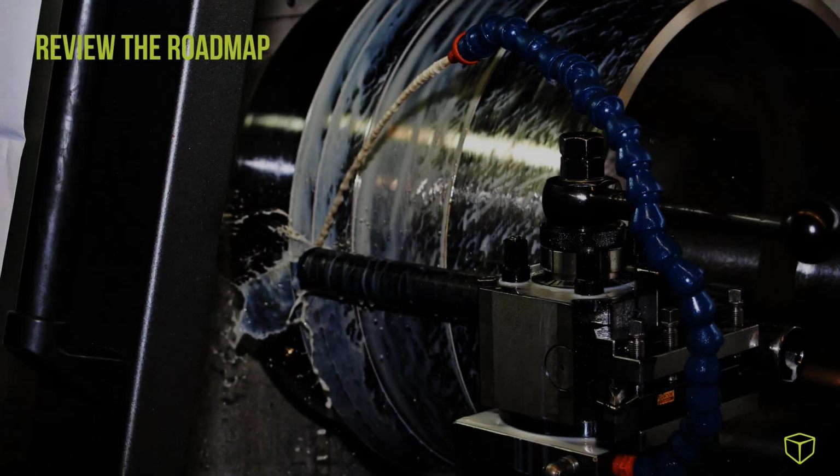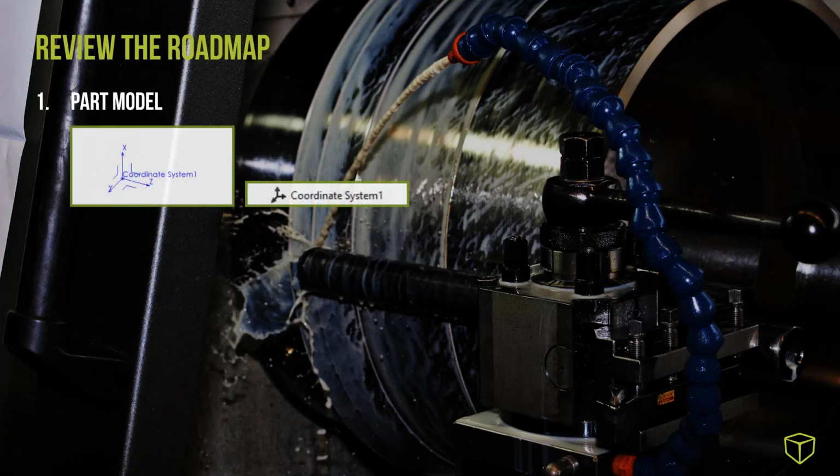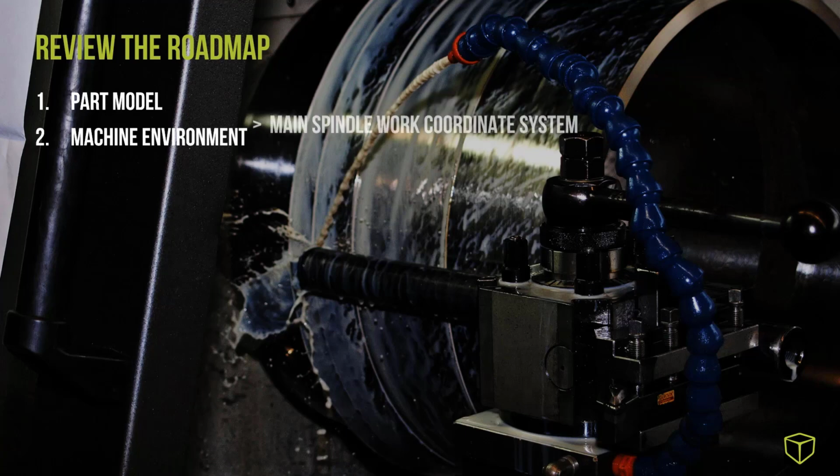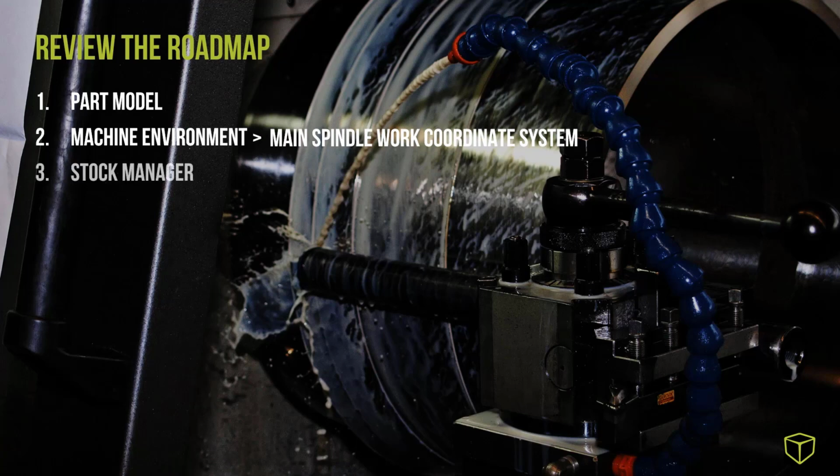So, let's take a quick review at the entire workflow of generating NC code using SOLIDWORKS CAM Professional and CAMWorks Interactive Feature Recognition. First is the creation, placement, and usage of a mandatory SOLIDWORKS coordinate system feature. Next, define the parameters of the machine environment, especially the assignment of the main spindle work coordinate system. Specify the material type, shape, and size within the stock manager.